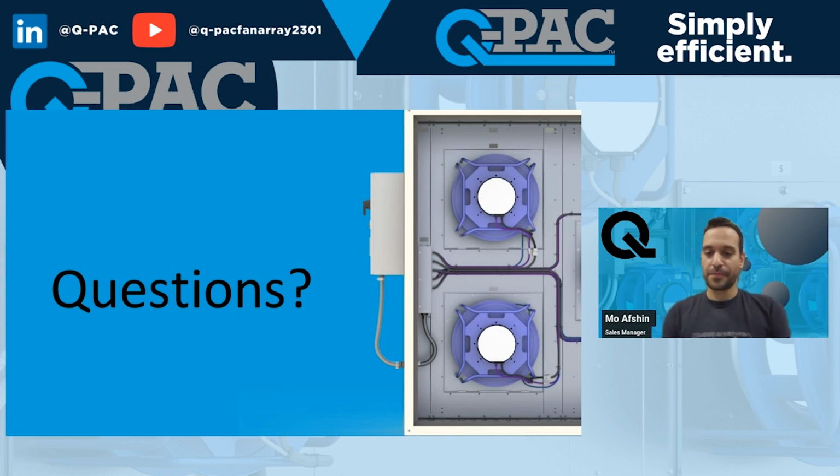Next question from Hugh. Will FEI then deal with the losses of a VFD/ECM drive? No. It is the fan and nothing upstream of the fan. You're correct, that does not include it. It does include the ECM drive, because the ECM drive is in fact included in the fan, but not the VFD. Perfect. And if any of you see comments from Mark James, he is our product manager, so those are legitimate answers, not just somebody messaging things in the chat. We do anticipate offering fan safety cages in the future.